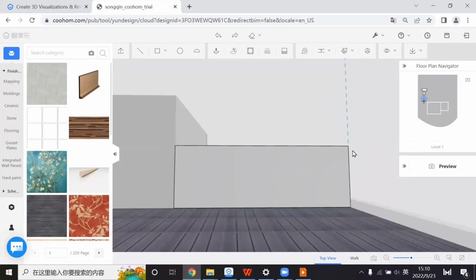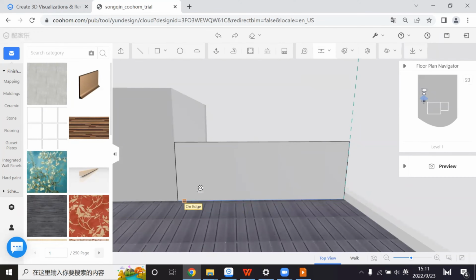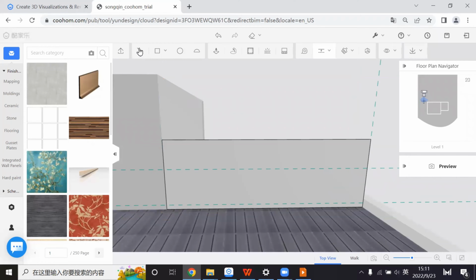But if you really have some exact requirement of the height gap, you can also use the guideline. Very easy sample. Let's see here. If my start point here is lower than the highest point, for example, let's say this only contains 100 millimeter, and here I need to go above, for example, 900 millimeter, then I can have this gap. And then I can use the line directly from intersection point to intersection point.